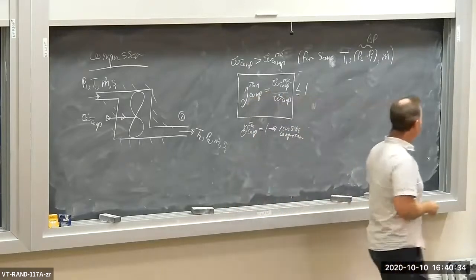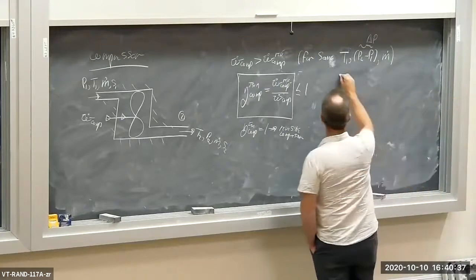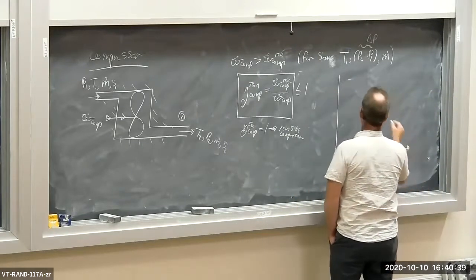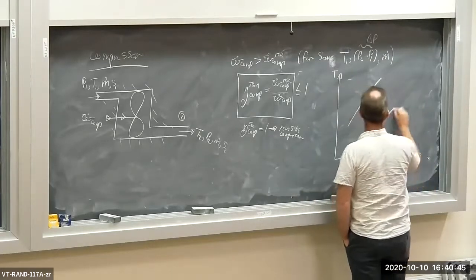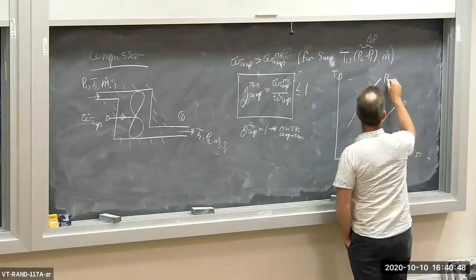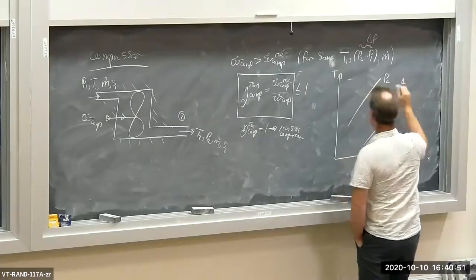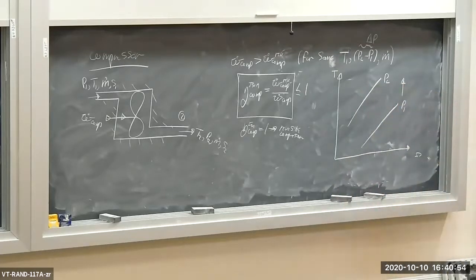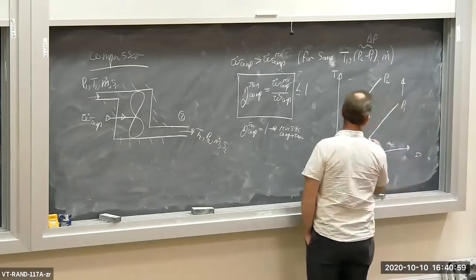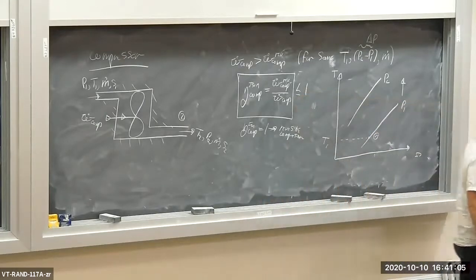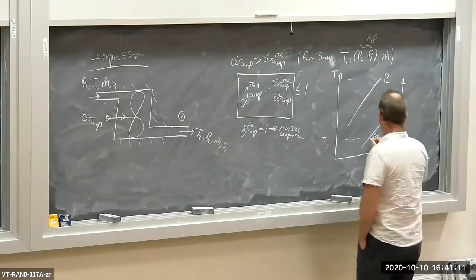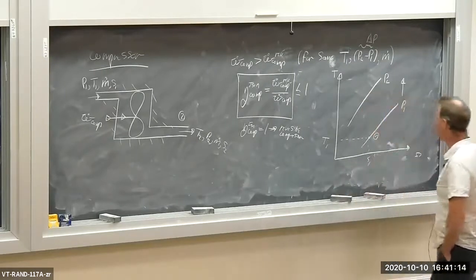Okay? Let's draw the TS diagrams for the reversible and the irreversible or actual compressor. TS. Same two pressure limits. So we're going from P1 to P2. So pressure is going up as we compress. That's what a compressor does. Pressurizes the flow. Let's see here. So state 1 is right here. So the compressor, both the reversible and the real compressor, start off at the same temperature T1 and the same pressure P1. And of course, we have an S1 right here.